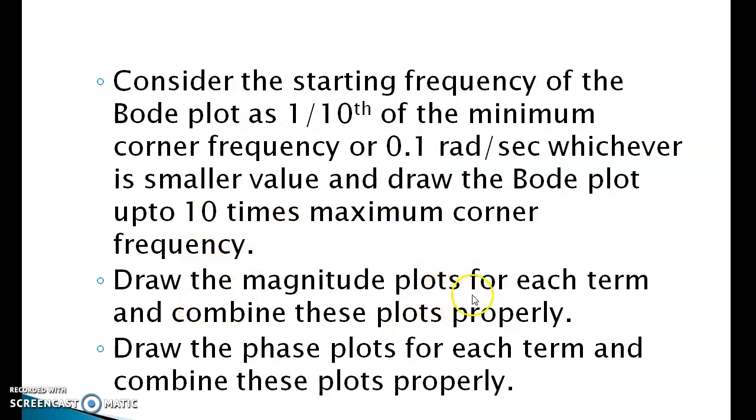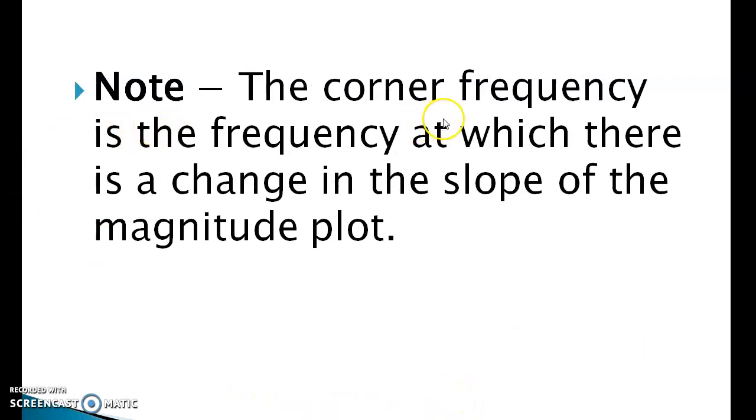Draw the magnitude plots for each term and combine these plots properly. Draw the phase plots for each term and combine these plots properly. Note, the corner frequency is the frequency at which there is a change in slope of the magnitude plot.